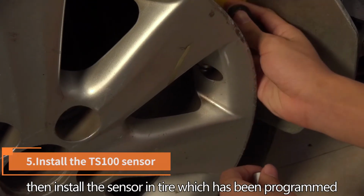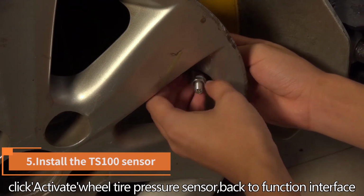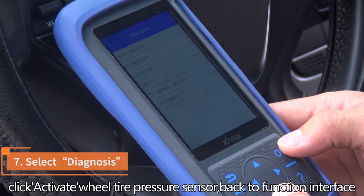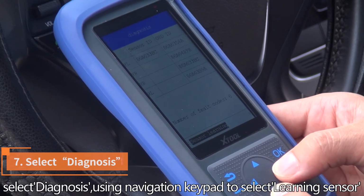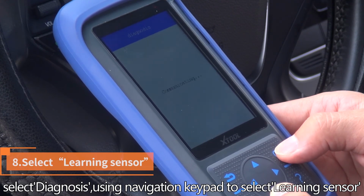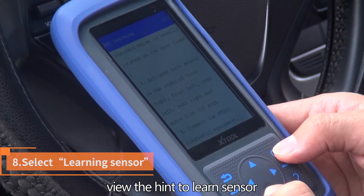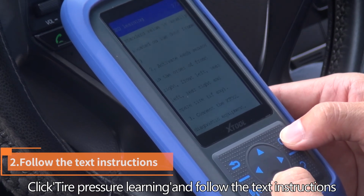Then install the sensor into the tire which has been programmed. Click Activate Wheel Tire Pressure Sensor. Back to Function Interface. Select Diagnosis. Using navigation keypad to select Learning Sensor. View the hint to learn sensor. Click Tire Pressure Learning and follow the text instructions.